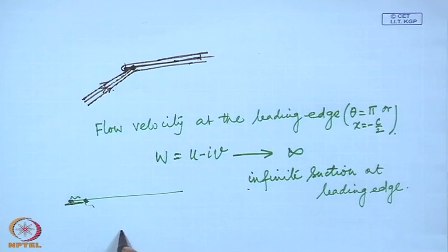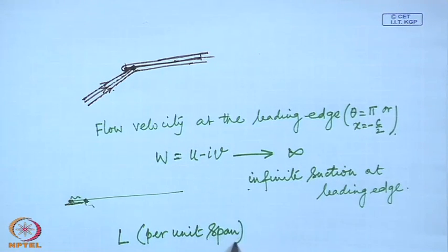How much is the lift force per unit span? Lift force per unit span. We have already derived the general formula for lift force. The lift force is rho q infinity circulation. How much is the circulation here?